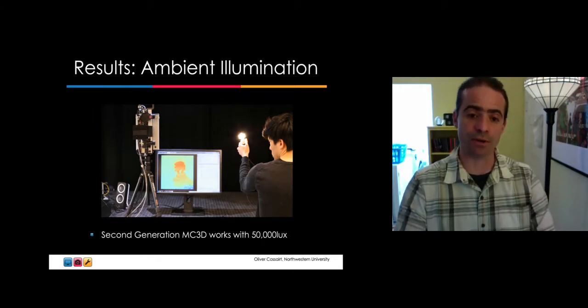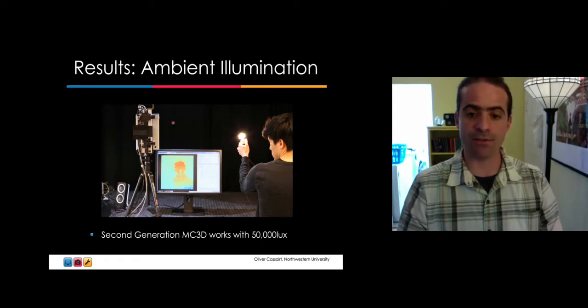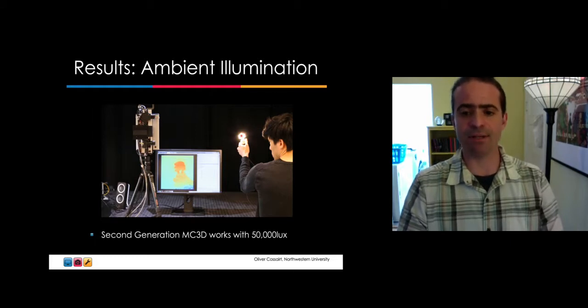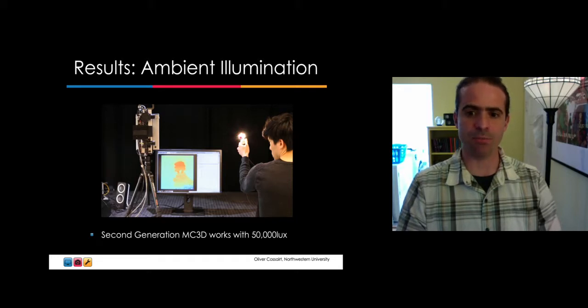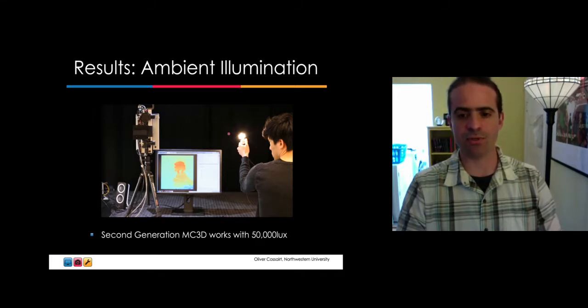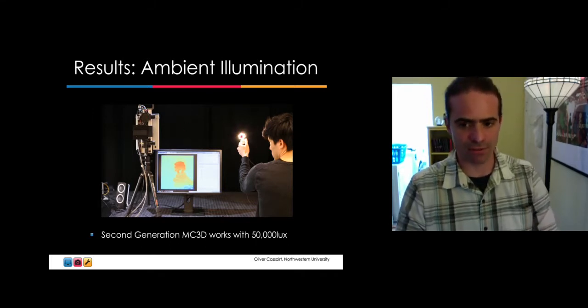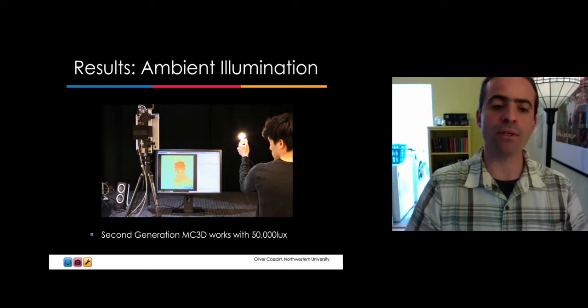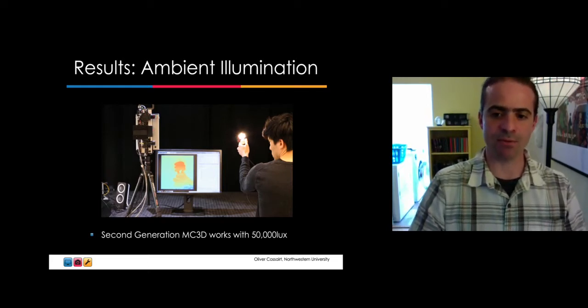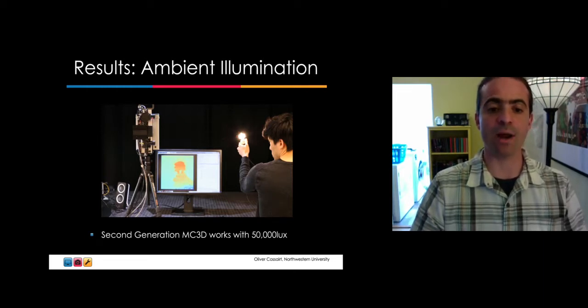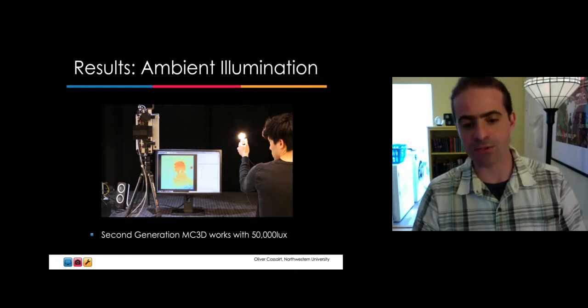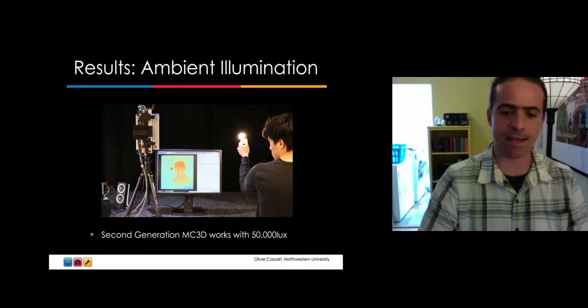So what I'm showing you here is an image of a laser scanner that's being projected onto this light bulb. And so this is an infrared source, so you can't see it, but what's happening is that a laser spot is being moved across the source. It's calibrated together with an event sensor over here that's capturing and looking at this image of this light bulb here. And it's only firing events whenever there's a change in intensity, which means that because the light bulb is not changing intensity, it's only seeing events fired where the laser projected its points. So as a result, you can apply this principle. You can actually scan the light bulb while it's on.